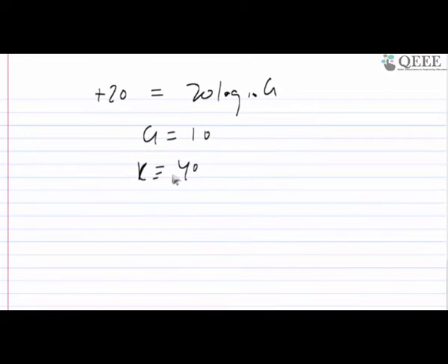From the plot, it says I can have a plus 20 dB extension, which allows my system to remain stable. So let's put the 20 dB as some gain G. From this it gives me G equal to 10, and this is the factor by which I can increase this constant, the gain K. Since I chose 40 and multiply by 10, it gives me 400.